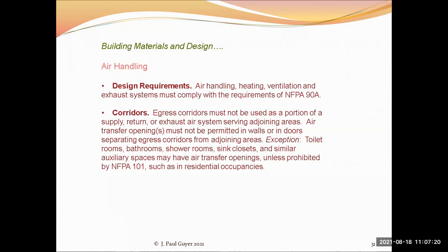This all depends on the configuration of the building and this sort of thing, but another tactic that can be used is through the duct configuration and the use of automatically actuated dampers, fire dampers, smoke dampers, to perhaps reroute, keep the fan that's pressurizing the HVAC system operating, but route the air from the space where the fire breaks out so that it is exhausted directly to the atmosphere. And so you're sucking the smoky air out of the building and exhausting it outside.